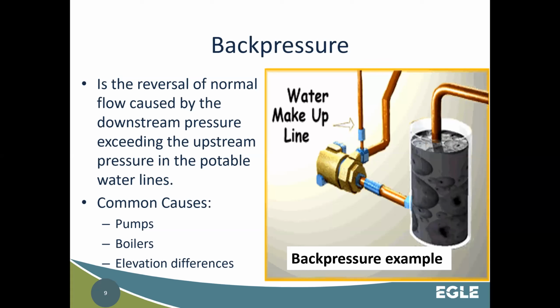Those pumps create a pressure. Boiler creates pressures because it boils the water, and pumps create pressure because they're a pump. Those will create situations of higher pressure within a house, a business, an industry than that of the water system. Most water systems in Michigan run anywhere from 50 to 65 PSI. It's not to say that there aren't higher ones out there, okay? I'm not saying that. There are, but 50 to 70 is like the sweet spot range